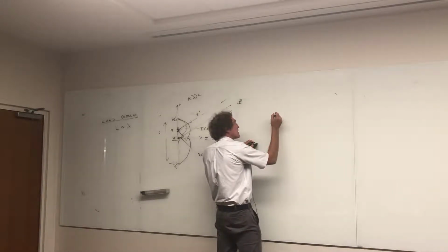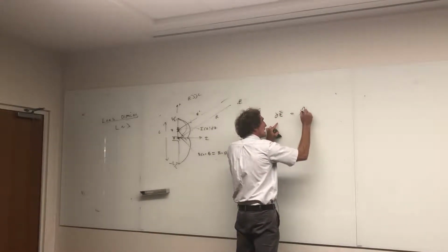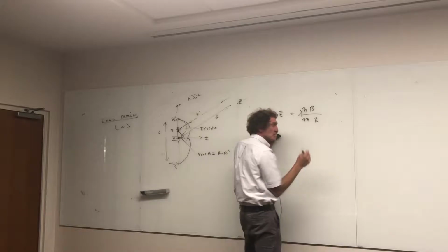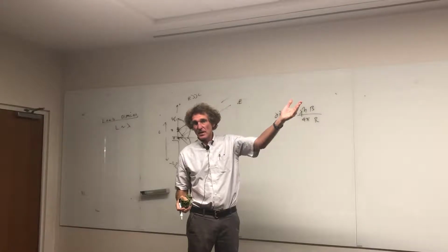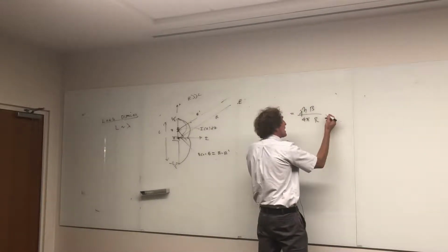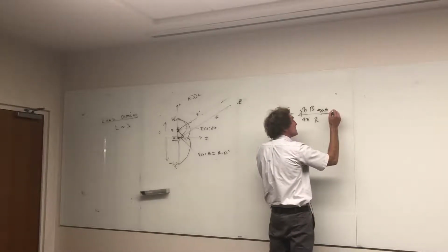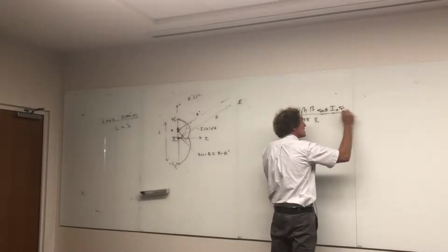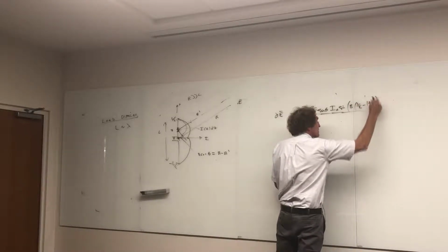Now I know the differential electric field for a short dipole. If I just put differential electric field, assume it's a short dipole, I know it's really j eta beta over 4 pi divided by distance r. Since r is about the same thing as r prime, I'll leave it as r. They're a long way away, got it? Now I take that, I know I'm going to have the sine of theta here, right? That's going to be involved. Then I have I of Z. Well, what's I of Z? It's I naught times the sine of beta times L over 2 minus the magnitude of Z.